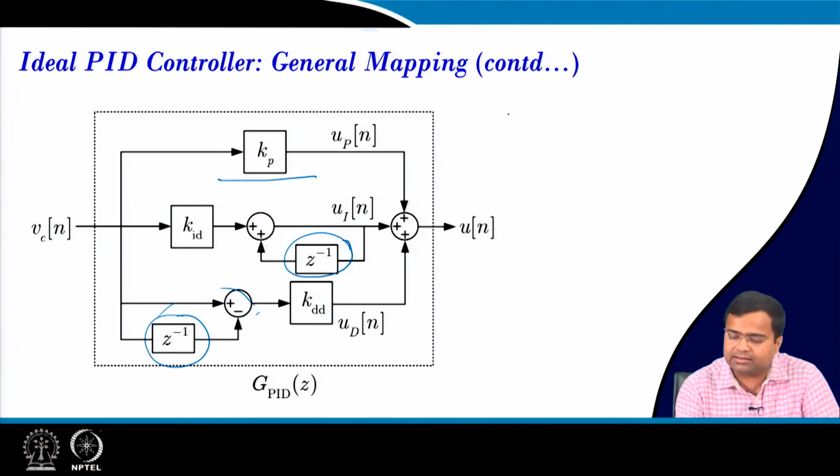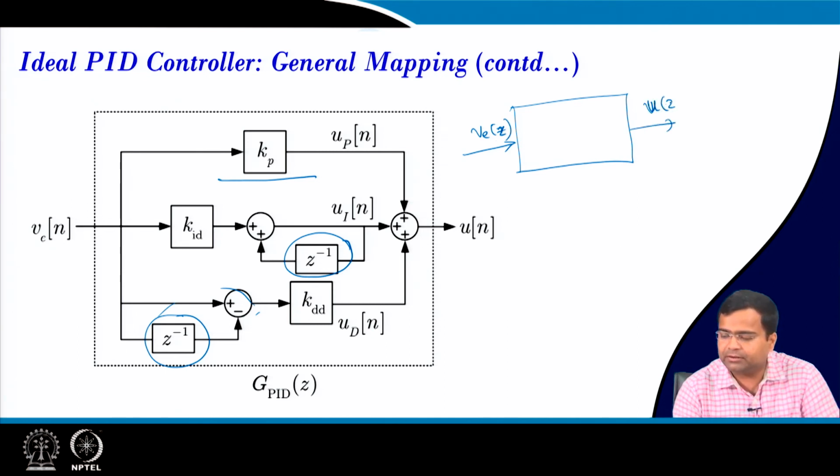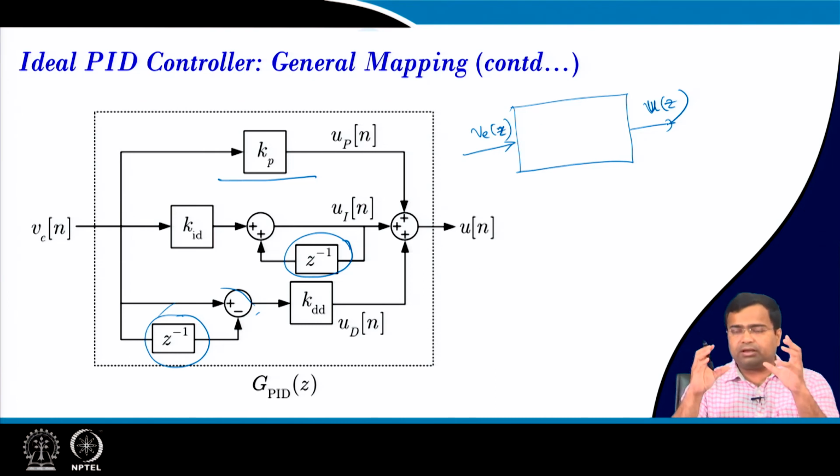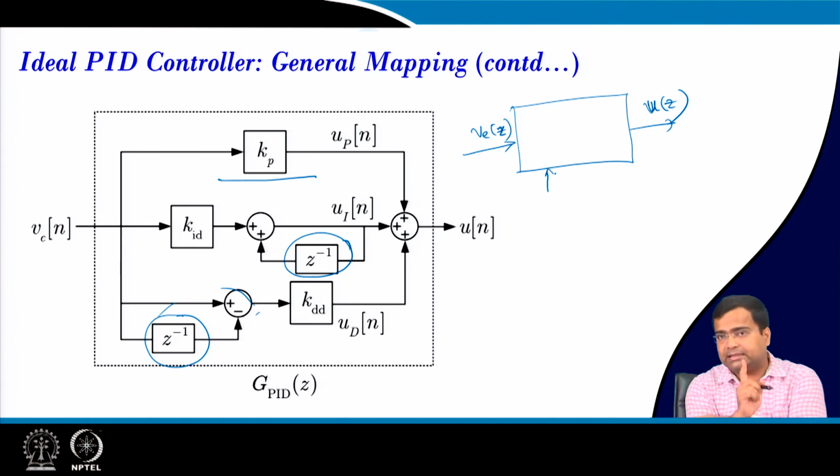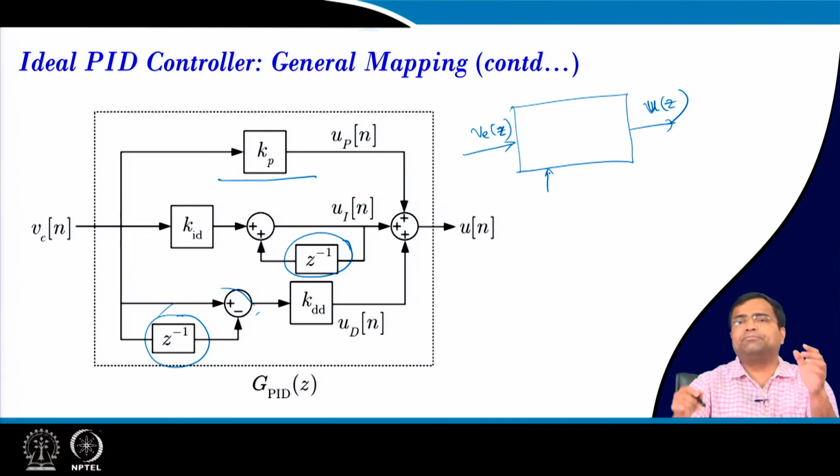So, one can write the whole transfer function as U(z) over E(z) in the z domain. But we have also learned that if we want to delay this signal, because we want to sample the signal at an edge of the clock that we want to customize, then if you write this transfer function directly in MATLAB, it will be difficult to manage the edge.